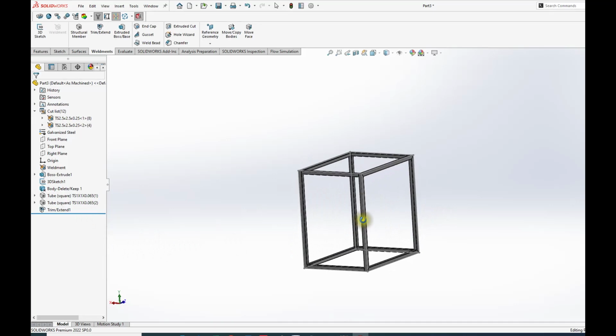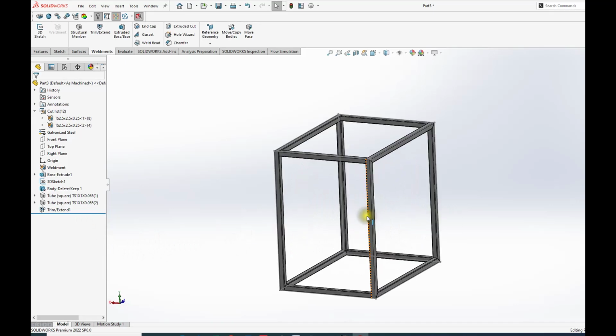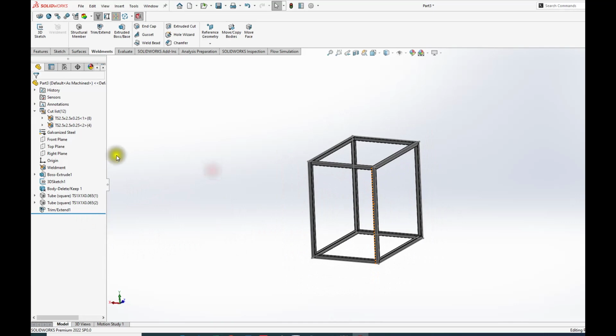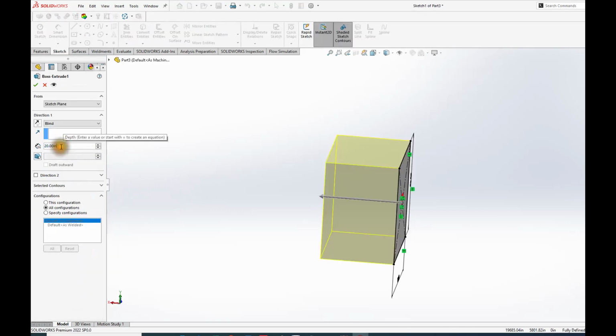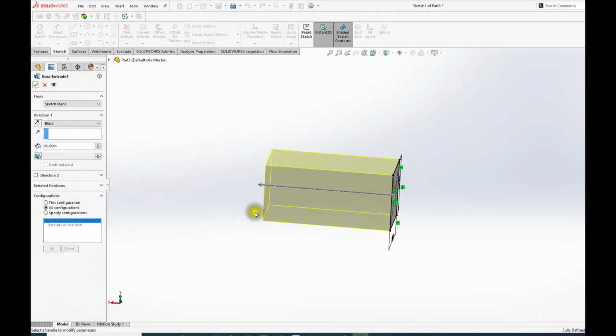And here's our body all together, very quickly done. And the nice thing is you eliminate one of the bodies. I mean, the main body was this one. You eliminate it as a body, but you still have it here. For example, if I want to do a modification because I don't want 20 for the distance here, and remember the distance of 20 is from this point to that point. That's the 20. So you want to increase this to 60. It's as simple as coming over here and doing that modification, and now, instead of 20, go back to 60 here, and you accept that, and then